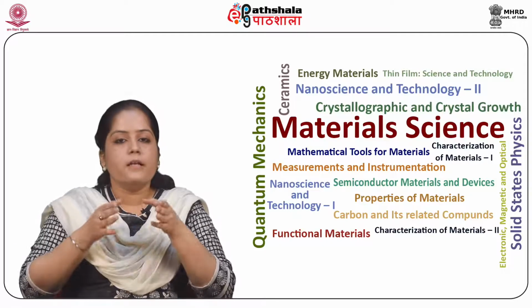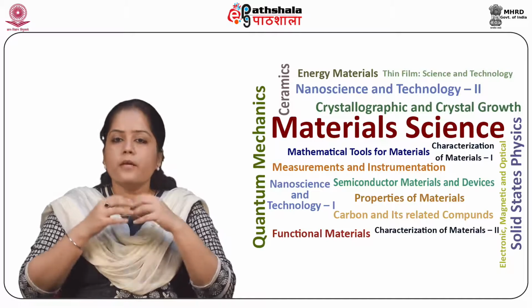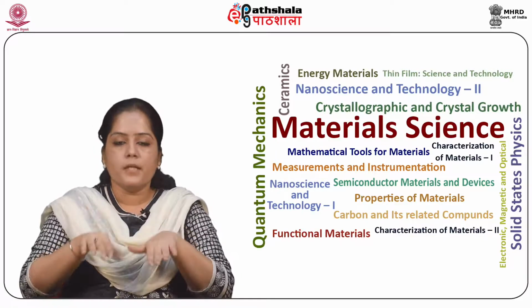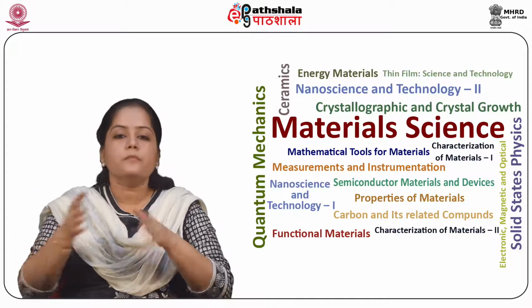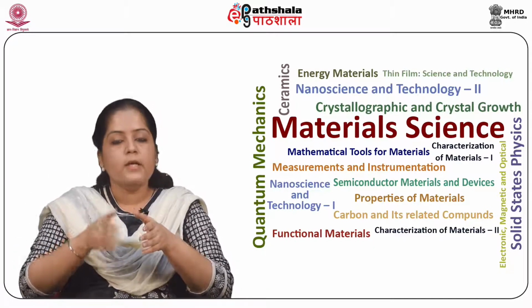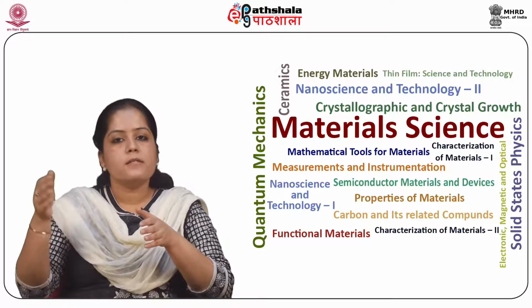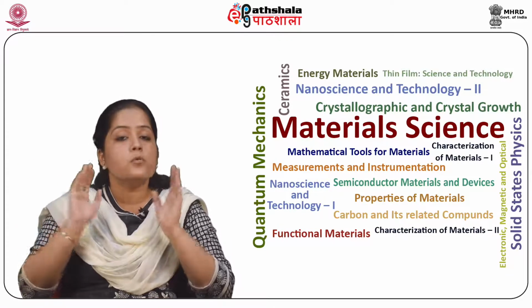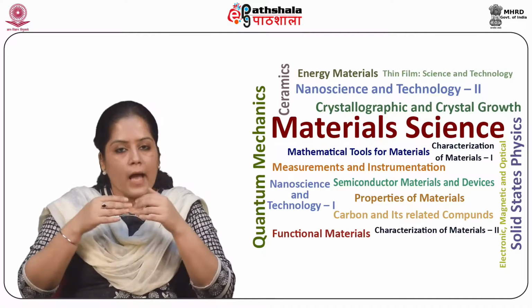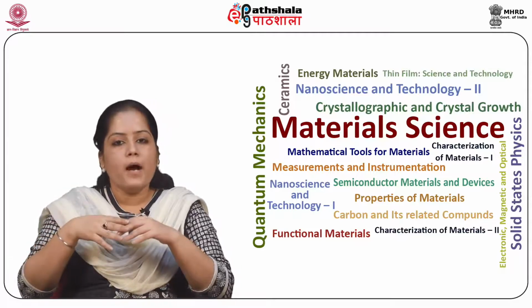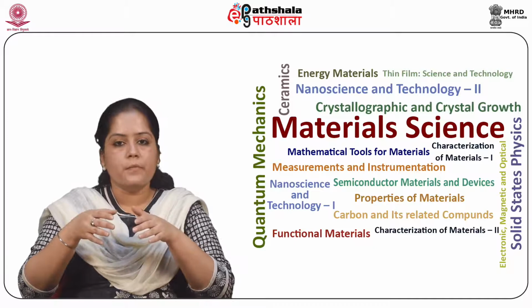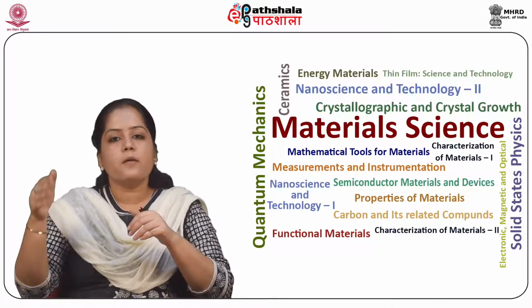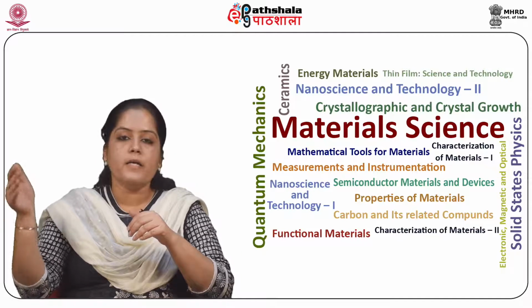Griffith crack, the energy balance approach. So the increase in the energy due to the creation of the new crack surface per tip equals 2 gamma a. So total energy change T equals 2 gamma a minus sigma square by 2E multiplied by pi a square. So the change in the total energy as the crack length increases by an incremental amount da: dT by da equals 2 gamma minus sigma square by E multiplied by pi a.